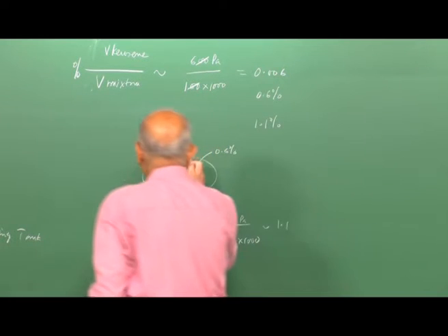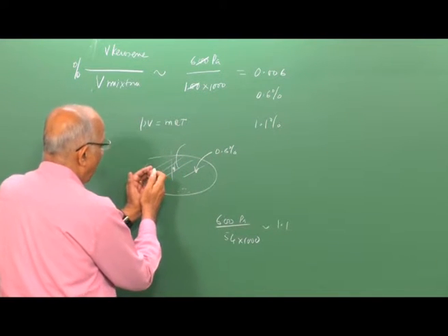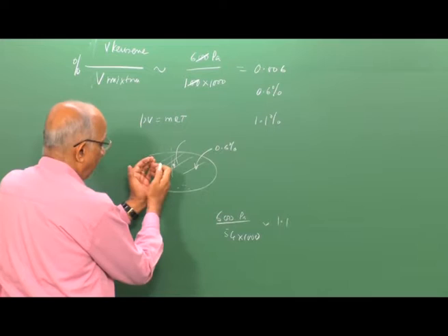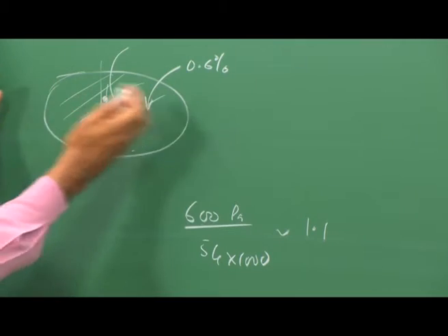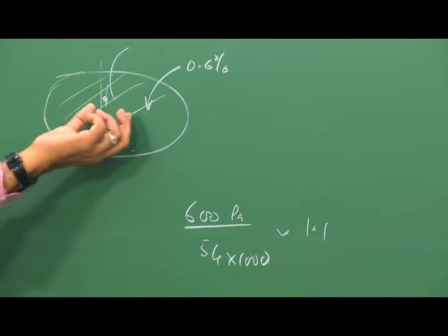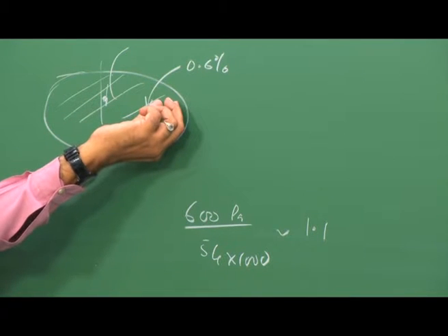That means you have a flammable mixture. Because of the spark which is generated, I could have a flame or a combustion, and I have energy release, and this is what causes the rupture of the tank. But we will do this problem again when we talk in terms of confined explosions, to be able to calculate how much pressure is generated.